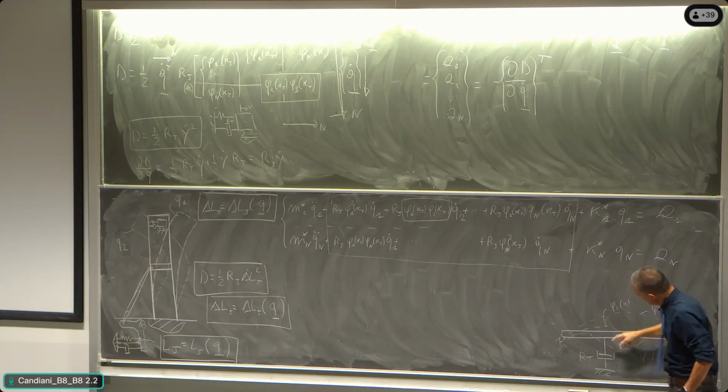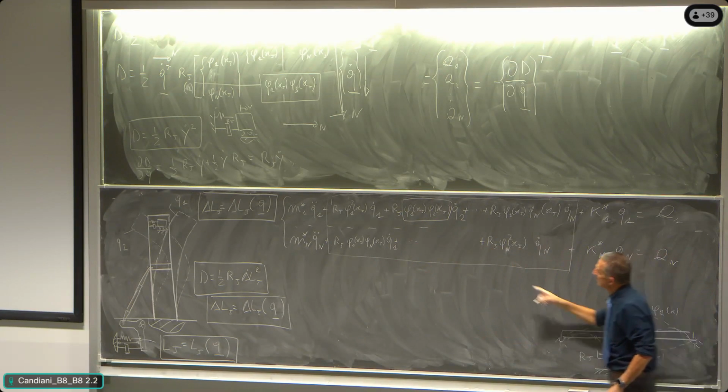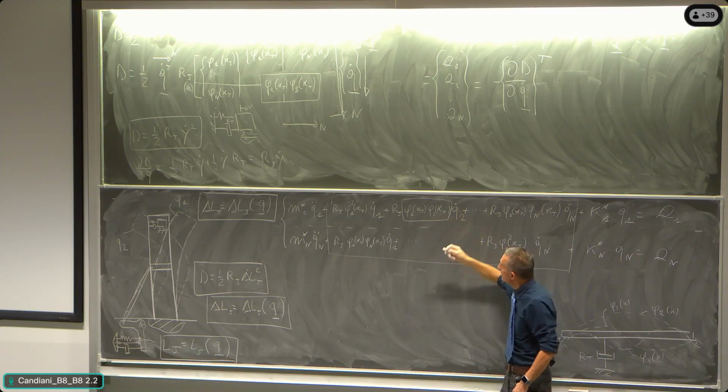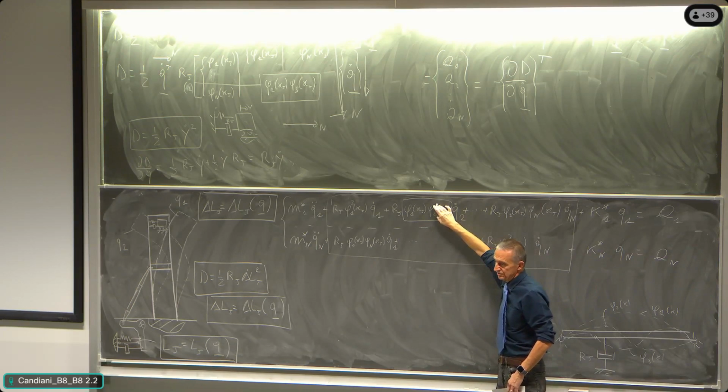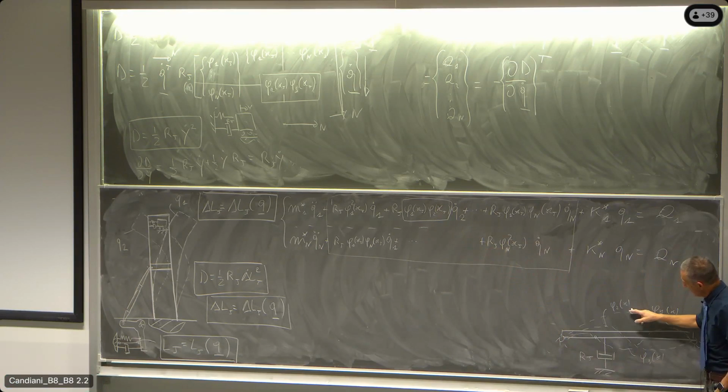If I am positioning the damper into a nodal location of one specific mode, at the node, if xj is the nodal location of a generic mode, this contribution is zero. If I am positioning the damper in the antinodal location, the contribution is maximum.